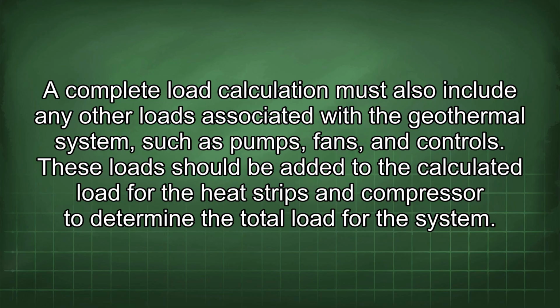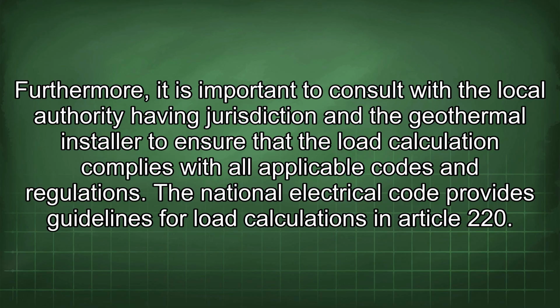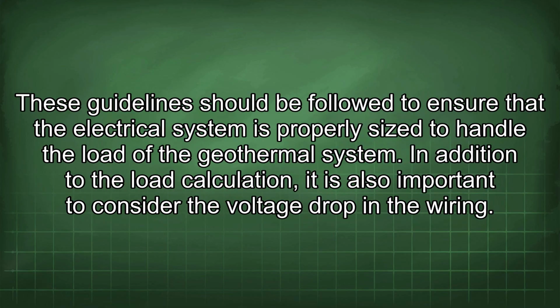A complete load calculation must also include any other loads associated with the geothermal system, such as pumps, fans, and controls. These loads should be added to the calculated load for the heat strips and compressor to determine the total load for the system. Furthermore, it is important to consult with the local authority having jurisdiction and the geothermal installer to ensure that the load calculation complies with all applicable codes and regulations. The National Electrical Code provides guidelines for load calculations in Article 220.